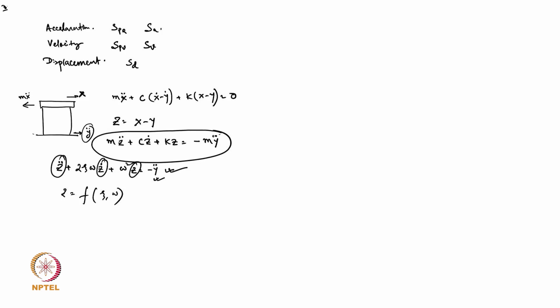Now suppose we have a ground motion, let's say this one. That is my y double dot with time. I applied that on a structure which has mass 1, stiffness omega square, and damping xi. That's the equation actually, so this represents this. I am implementing this motion at the base, and at the top I am calculating the value of z. So I will get 3 responses.